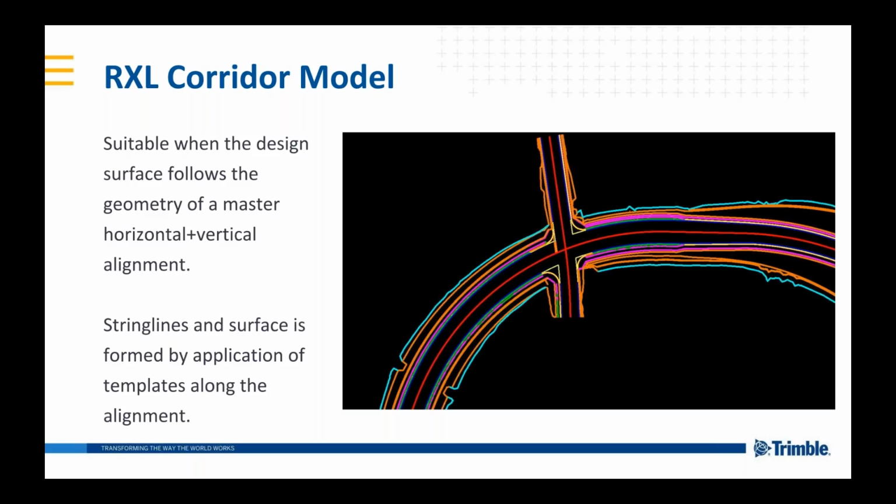And in this case, we do have an intersection shown here, a fairly simple one. As long as that doesn't get too complex, we can still model that reasonably well with the RXL format using one road model for that main line that flows east-west there, and then secondary alignments for that side road that we cut out and put in there as well.